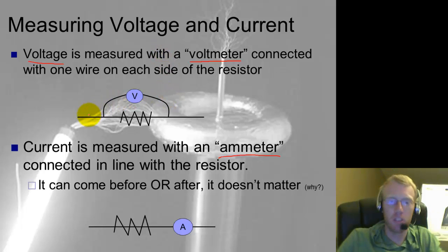So you can say the voltage across something is something volts. In order to measure the voltage across, you need to put one probe on one side and the other probe on the other side, and what it's measuring is actually the delta V between the two tips. Okay, so if you put both tips on the same side, you're going to get a delta V of 0 because they have the same voltage on this side and they have the same voltage on the other side. It's only across it that they lose voltage, aka lose energy,